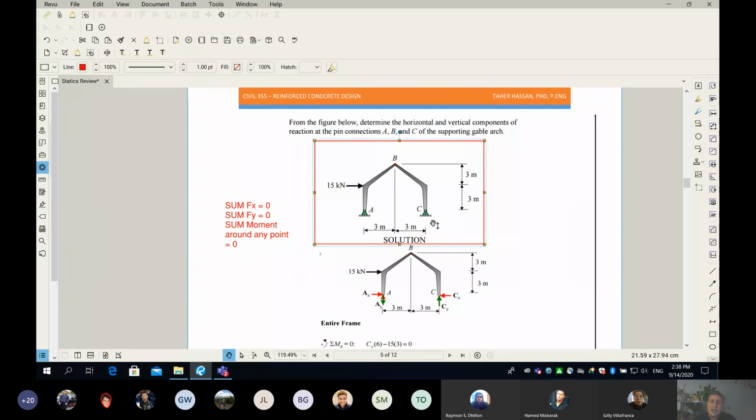Hinge. Okay, very popular in structural engineering. 3-hinge frame. When we build a structure, it's not really one of those. It has to be a series of those, a series perpendicular to your screen, and we simply create a 3-dimensional structure. But when we analyze the frame, we typically don't analyze in 3D. It's more complicated, and it probably requires a computer. And so what we do is we take the 3-dimensional structure and abstract it into 2-dimensional elements, like, for example, the frame you see.